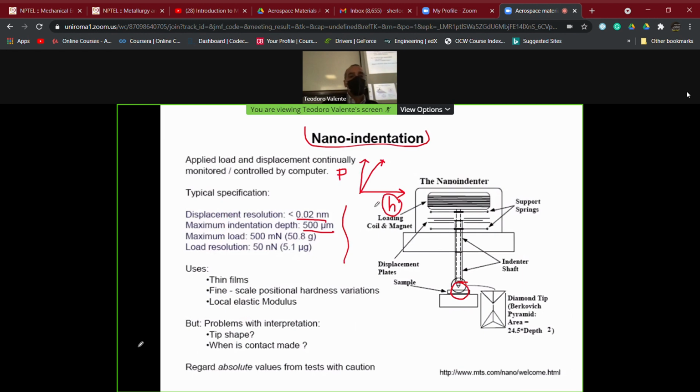The depth of penetration of our tip gives us both elastic and plastic deformation, since after this testing technique the impressed area still remains on the surface. And so when we are unloading, if we record the unloading curve, we can expect that the material's surface behavior is something like what we have already seen when we were discussing the stress strain diagram for bulk materials.